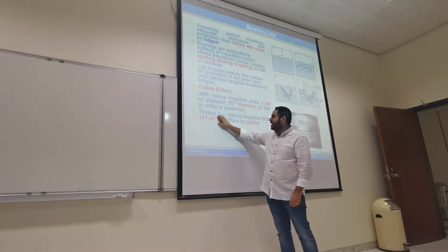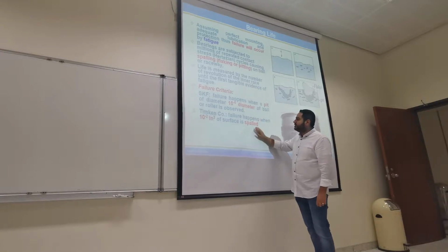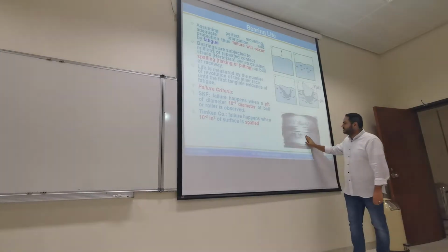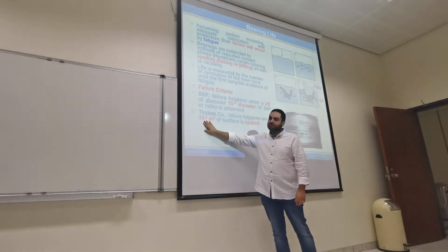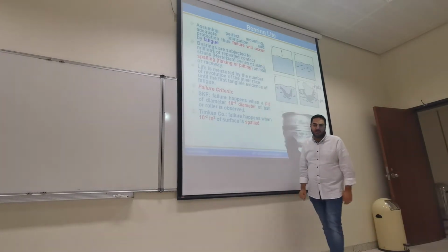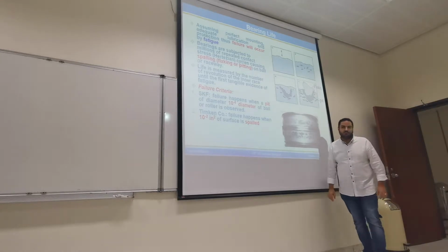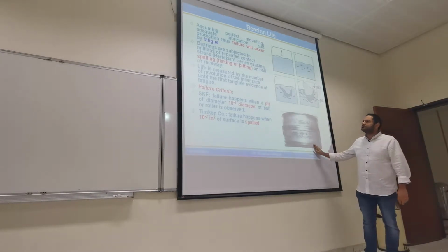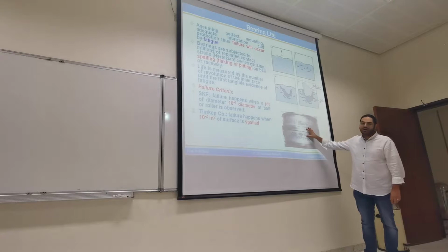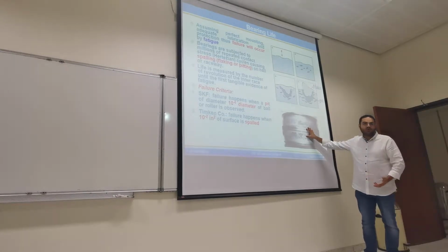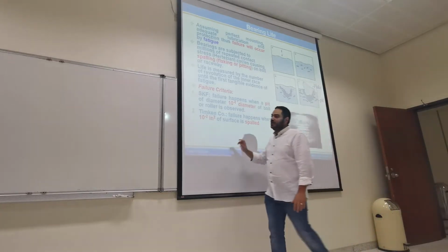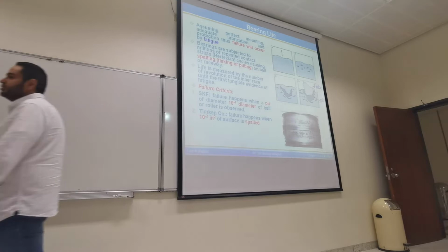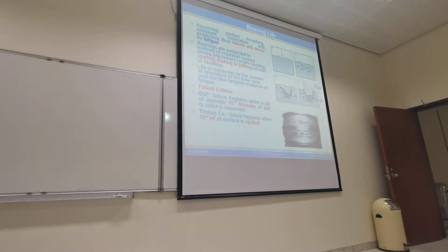Other companies have different criteria. They look at the surface of defects. If the surface covers 10 to the minus 2 of an inch square, they consider the bearing reached its final life or failed. Does that mean the bearing cannot run? No, the bearing still runs, but it is at a stage where we need to replace it. So these are the failure criteria when we consider fatigue phenomena.